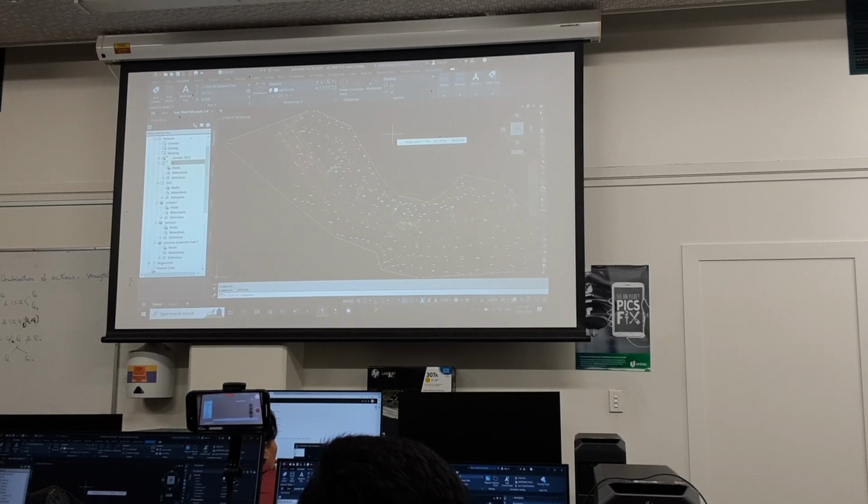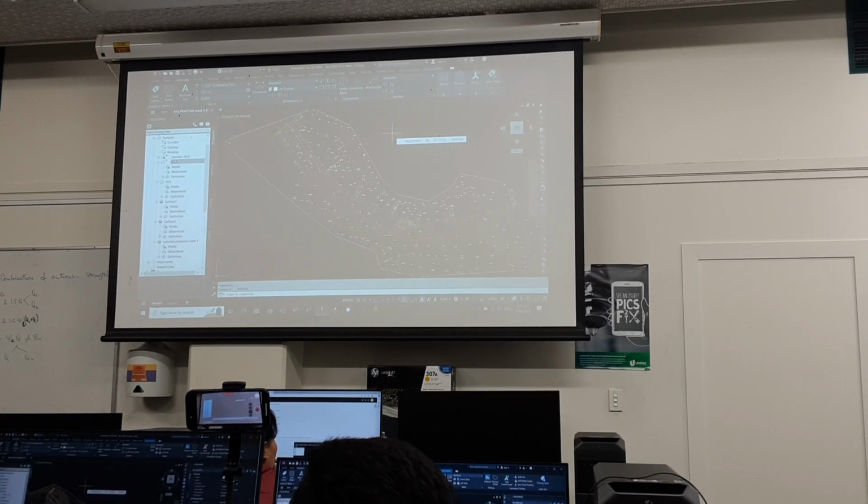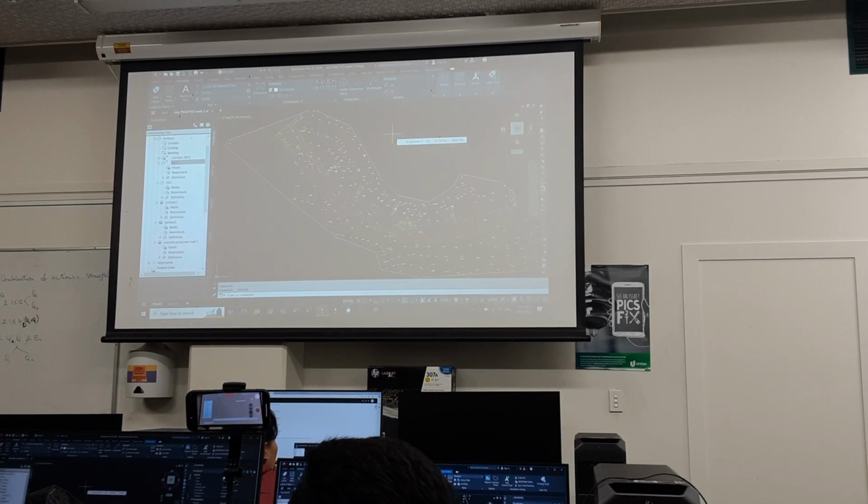Imagine driving along and there's a huge mound, 5 metres high, but it doesn't fall on a cross section and you just assume it's flat. Well, your volumes are all going to be completely wrong, aren't they? So you would be asked to do one where the mound is. Same with the gully.